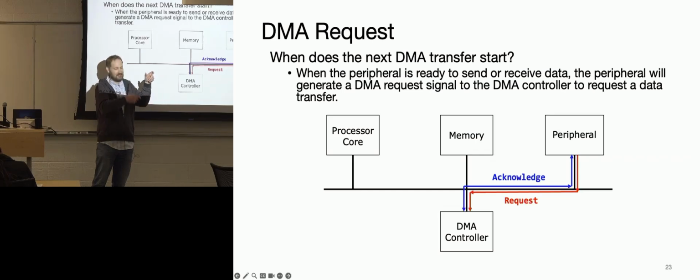So a way to do this instead is you have 2 buffers. They usually call them in code ping and pong. And so you get an interrupt that says, when I've hit the end of this buffer, then tell the core what to do, and then it automatically switches over to the other buffer. And so now, while this one's filling up, the core knows, okay, I've got to go process all this data, because when I come back to the first one, it's going to overwrite that data. So it's just a data structure that, with a little bit of hardware support, helps keep track of what the fresh data is.